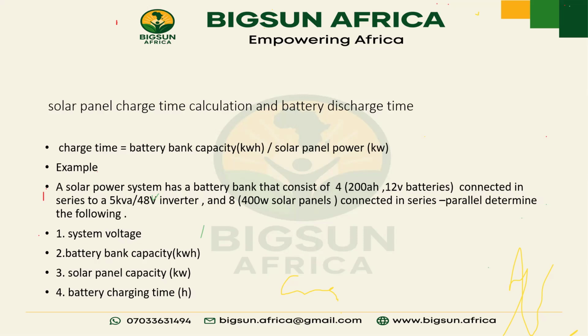So this is 17 kilowatt hour all over 6.6 kilowatt, right? In normal calculation, if you put 17 kilowatt hour over 6.6 kilowatt, you see that the kilowatt is going to cancel the kilowatt up. So you have 17 divided by 6.6, which is going to be 2.57 hours.